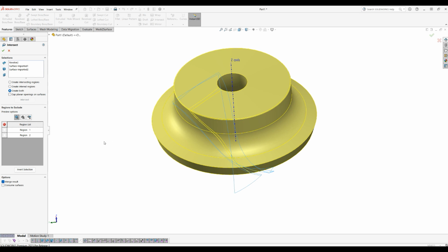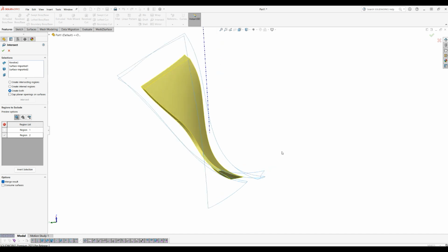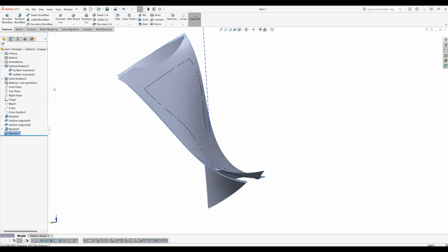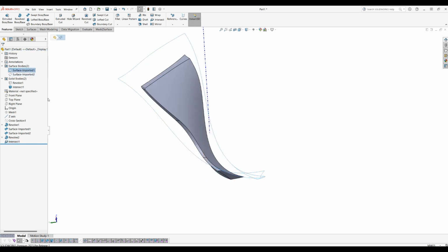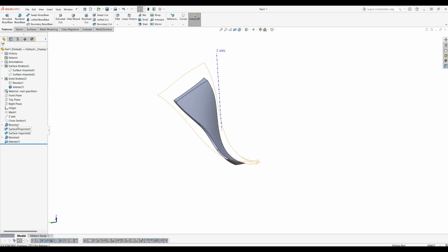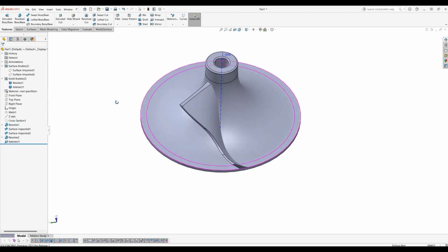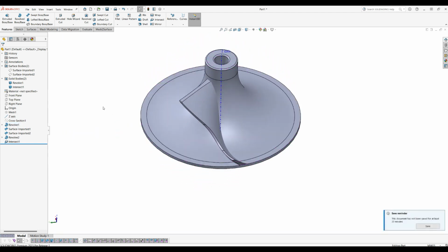So I created the different parts, and what I'm going to do, click on this one to make sure that SOLIDWORKS removes this, and as a result it will be one single solid body, which is the result of the intersect. In this moment I will just hide my two surfaces, I no longer need them. We can enable now our main body, the revolve one, so you can see how far we've been. And before I continue, I will just select my body, and what I'm going to do is create a circular pattern.